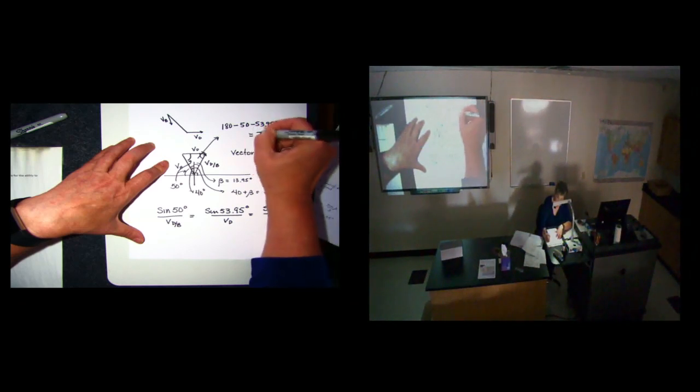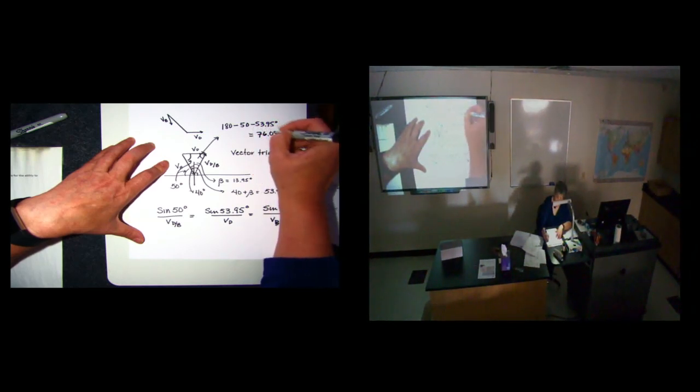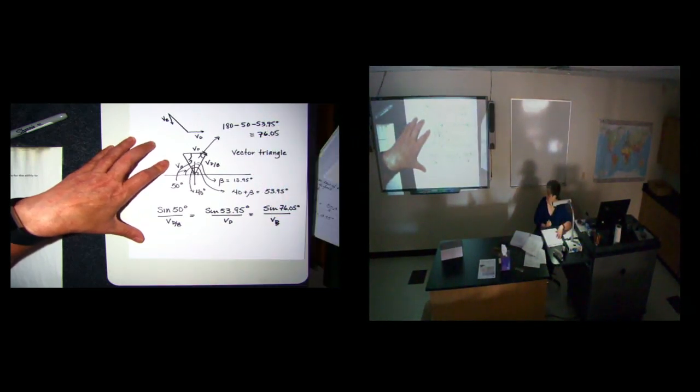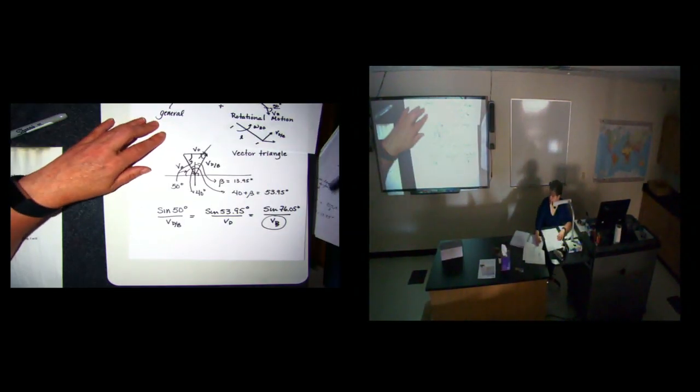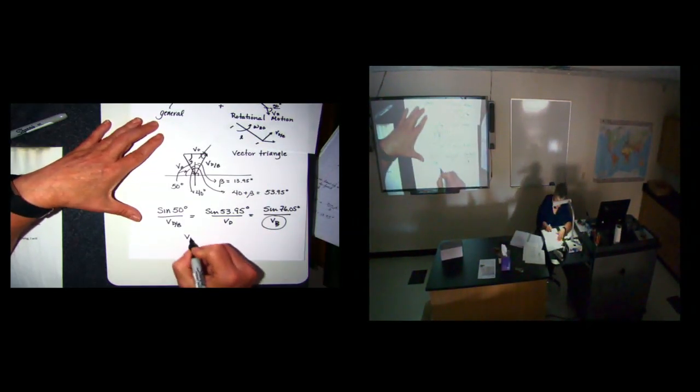And vector DB is going to give me 495.9 inches per second. And then VDB is just R omega BD. So I'm going to take my VDB divided by R. It's going to give me my omega BD. And this gives me 62 radians per second.